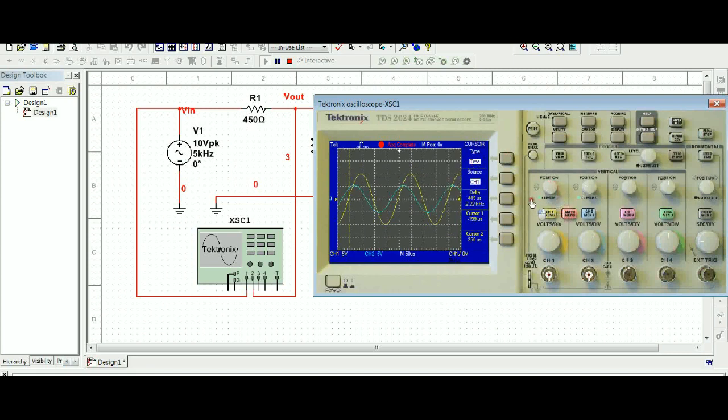So what I'll do is pull this out until I hit crossover on this waveform. Now, the reason I'm using crossover is because the rate of change, that is the slope of a sine wave, is maximum at crossover. It's very easy to set the cursor on that point compared to the top. You can see here that the slope, which would be a tangent to this, well, it's kind of hard to figure out where it exactly is, whereas with the crossover it's more obvious. Next, I'll look at my other cursor and bring him out and set him at crossover on the blue waveform. And it would be right there.